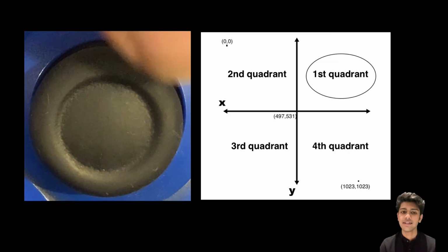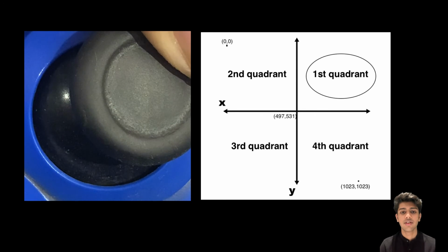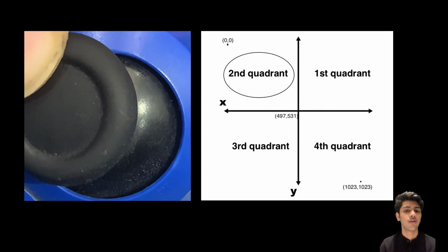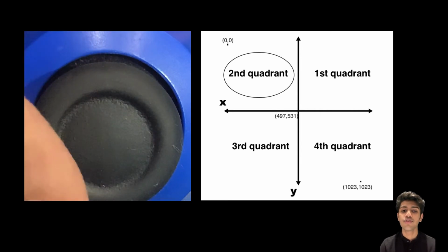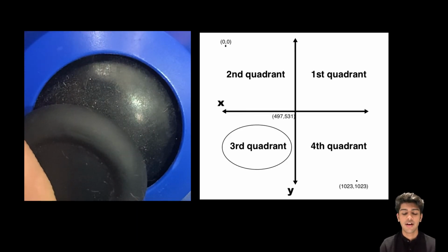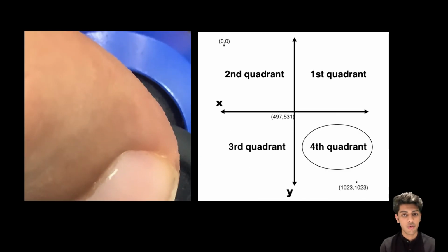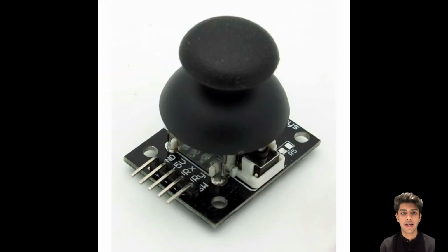this. So basically, the joystick can be thought of as a Cartesian plane which has x and y coordinates. And as you move the joystick around with your thumb, the coordinates change. The way we get these coordinates from the joystick is using the analogRead function.